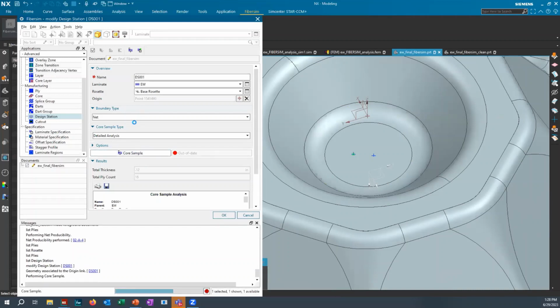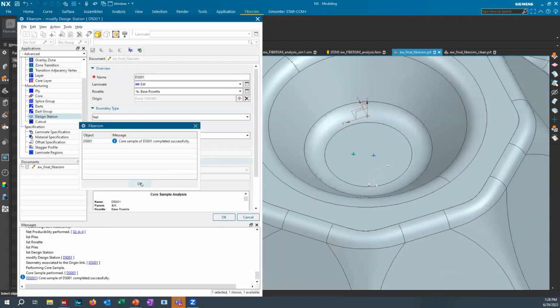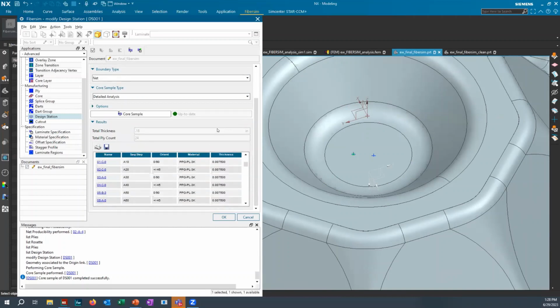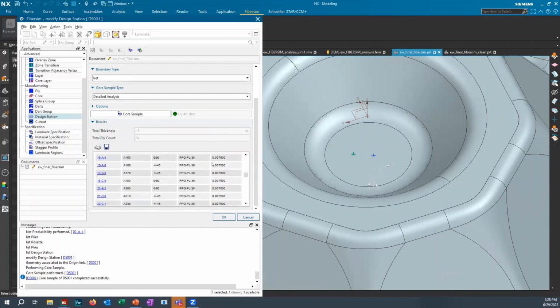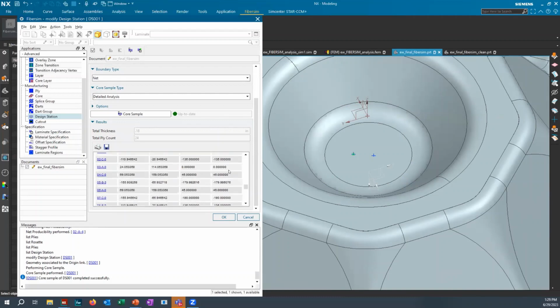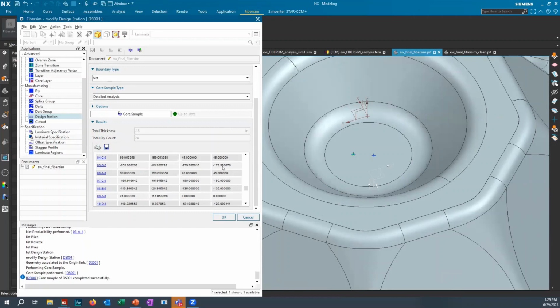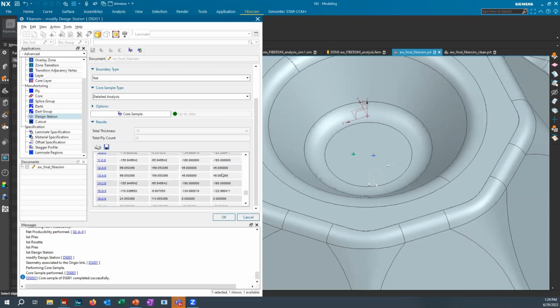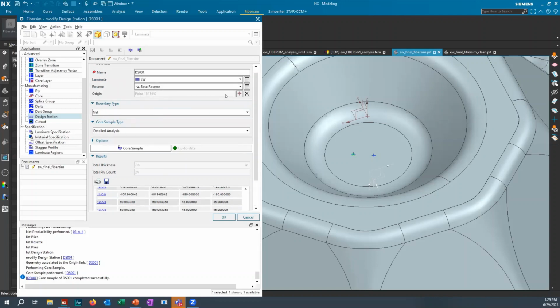And what we'd expect is a relatively low error in the angles between each other. So here we have 24 plies as defined by the analyst. Again, we have about a proper percentage of 45s and 90s. But the one thing we notice here as well is that for the most part, these are relatively close to either 0, again, this is minus 180, and 45. So we're getting a relatively consistent ply layup.